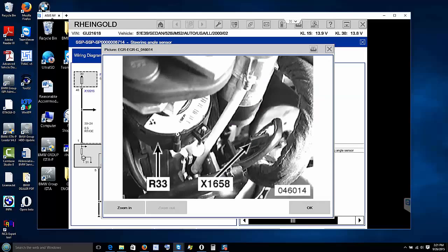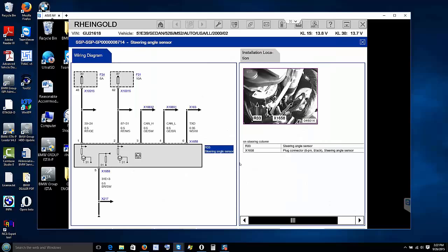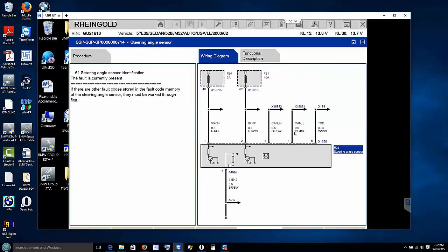Yeah. Okay. So this steering angle sensor probably looks like it's either outside the vehicle and it is attached to the steering wheel rod. You know what I mean? Yeah. So maybe that is, this is a 2000 BMW, so maybe that is where they put the steering angle sensor. So maybe that has to be changed. I don't know yet, but go through the test procedure first, and then it will tell you what must be done. And let us click that away.